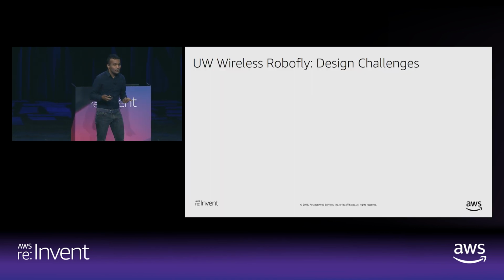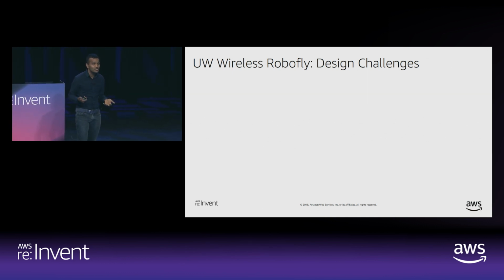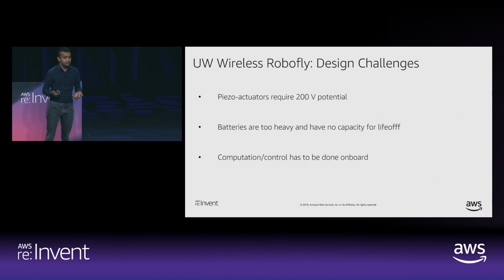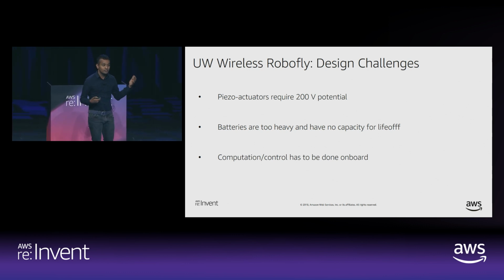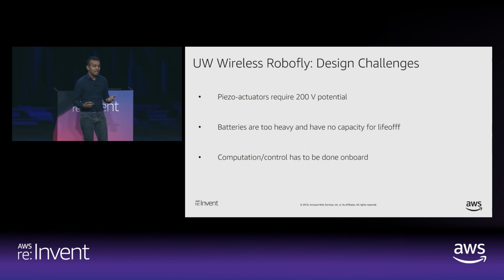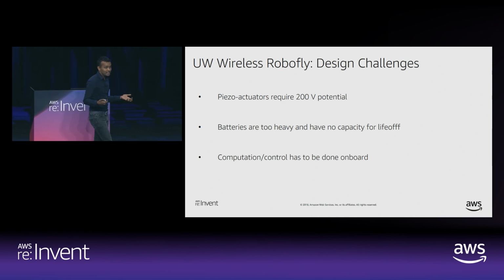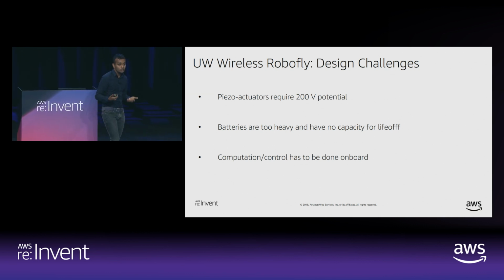It turns out, even to achieve this kind of liftoff, you need to address a significant number of technical challenges. In particular, the piezo actuators I talked about require voltages of about 200 volts, which is really hard to get at these tiny sizes. Second, batteries are pretty heavy. If you want to move something, you need significant power, and if you're going to use batteries, this thing cannot really carry huge batteries. And finally, you need to have computation and control, which again has to be done on board.